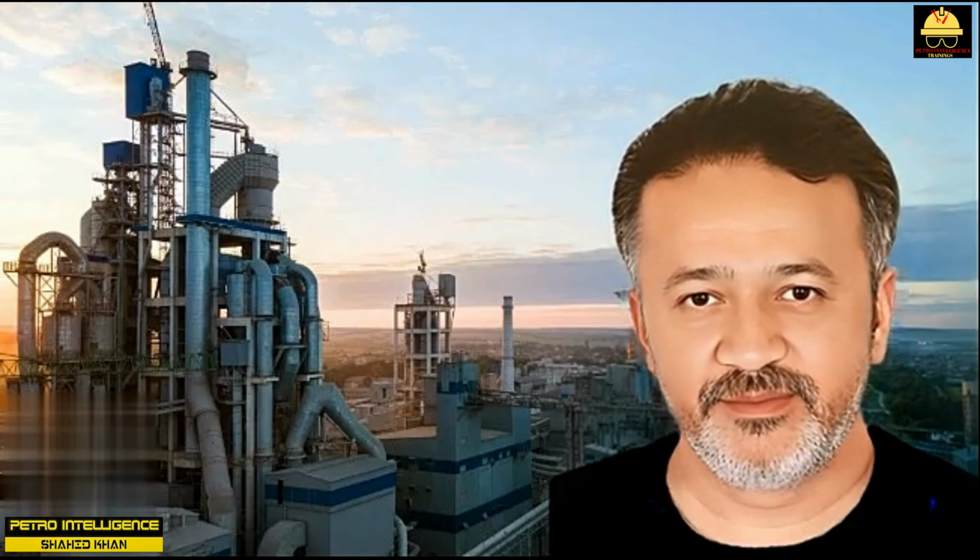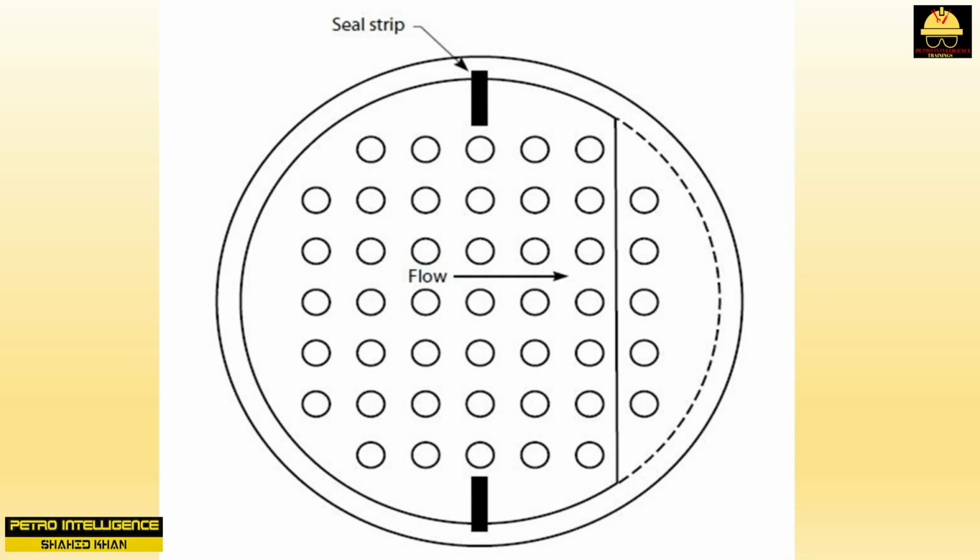Shell-side seal strips. See if you cannot find an old tube bundle lying around your plant. Many such bundles have pairs of metal strips set around the edge of the tube bundle. These metal strips are typically 0.25 inch thick and 4 inch wide. They extend down the length of the tubes. As shown in picture, they are inserted in grooves cut in the tube support baffles. These seal strips often increase heat transfer efficiency by 5 to 10%.